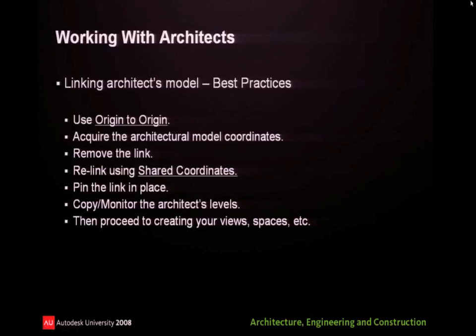Yeah, that's a good question. Okay, let me address that. He's asking how do you get the piping and plumbing on the sheet. Well, right now our delivery method is we have separate sheets for AutoCAD. We tried it the other way, where we basically had a model or base file for the AutoCAD plumbing, and we brought that into the Revit environment as an import, and it slowed it down a lot. And we actually cut the model in half.